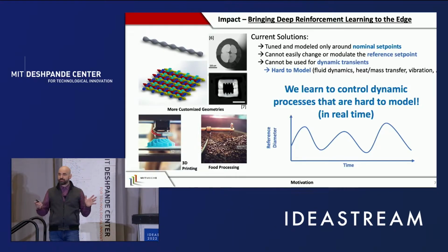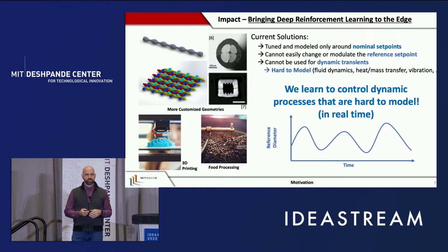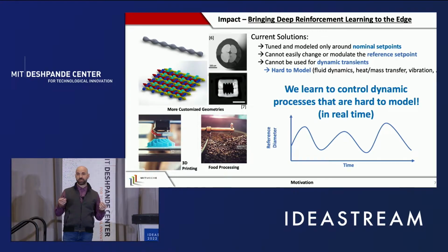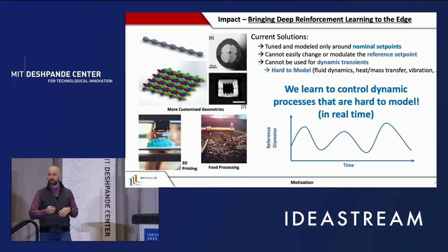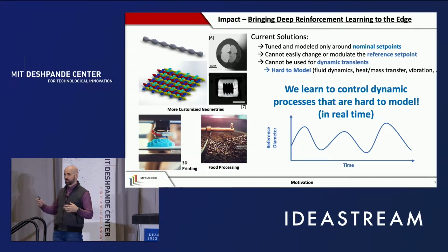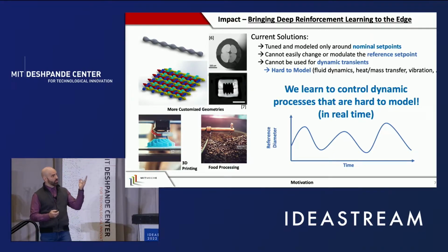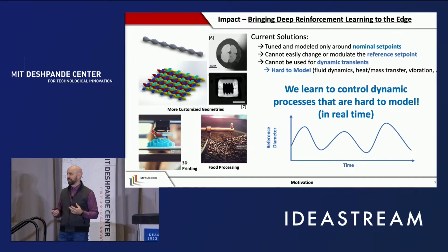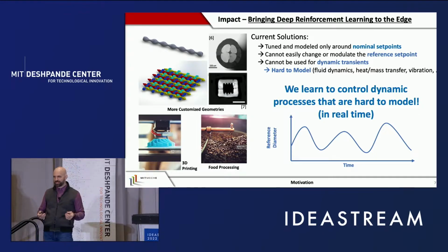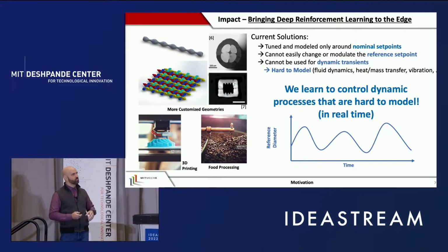Now, that's great, but there are some unique challenges associated with processes that have a lot of drift, either in the materials, or that are complex physically. If there's a lot of complex thermal, fluid, electrodynamics going on, operating a controller around a set point benefits if you have a good model of your system. Some of these systems are really hard to model. Even fiber draw is a complex heat transfer, mass transfer problem that you could write down the coupled differential equations for and come up with a great model. But it's hard to do from first principles.